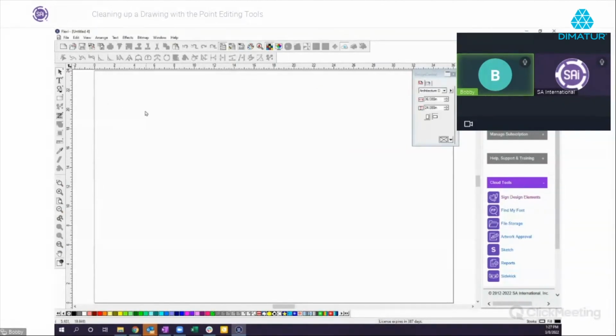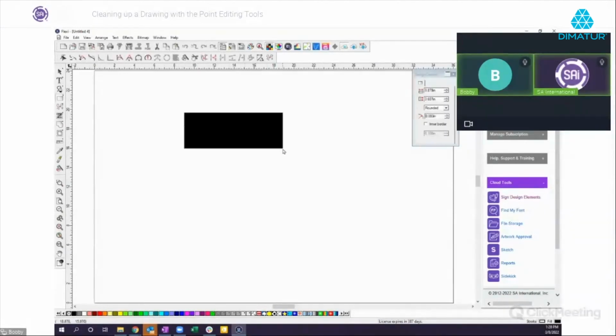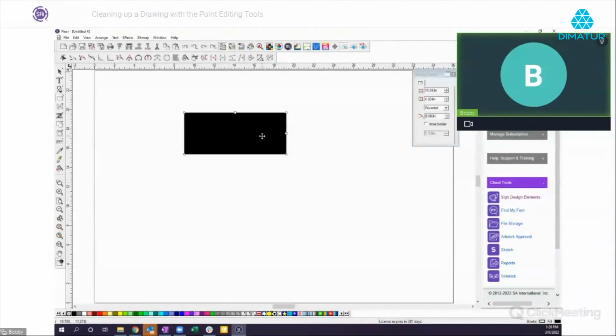Yes. Alan has a question. He says, I keep coming back after exiting and the old font and color is still there. How do I change those? All right, that's one that a lot of people have trouble with, and it can get very frustrating. All right, so black is my default color right now, okay? The easiest way I've found to change that is, I'm going to click on here, and I'm going to have nothing selected. And if you'll notice down in the bottom corner where it shows my fill, I'm going to click a different color. I'm going to click yellow. Yellow is now my fill color. So now when I draw a rectangle, it'll be yellow.